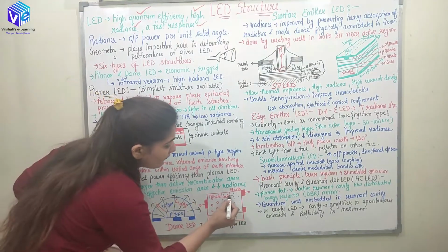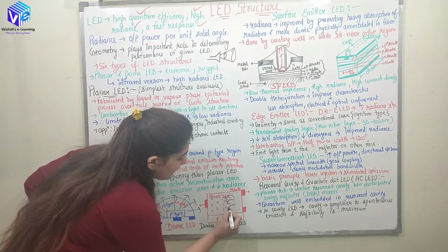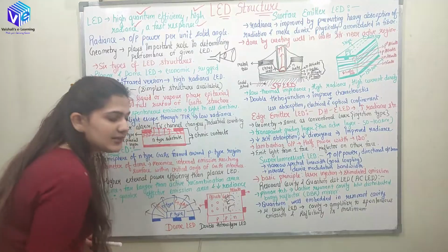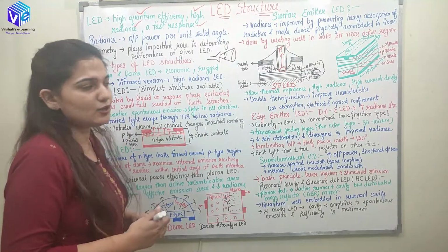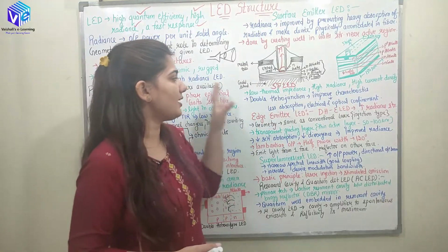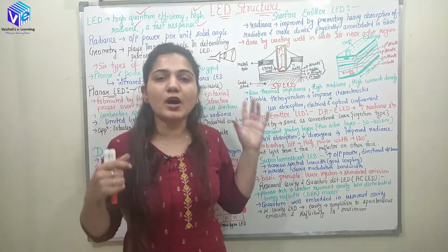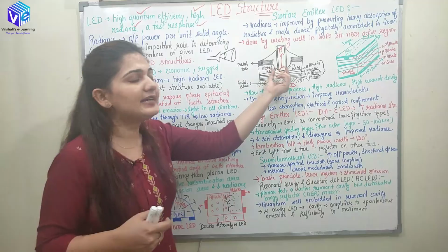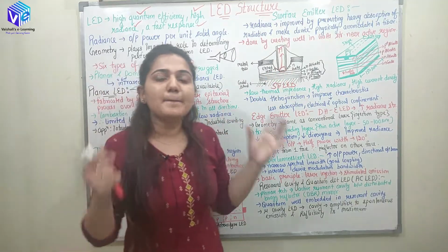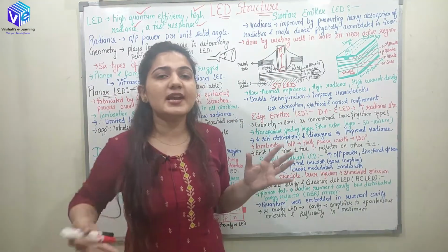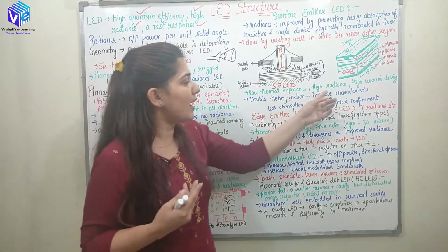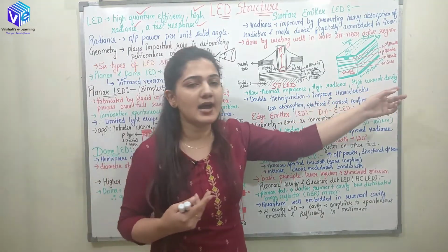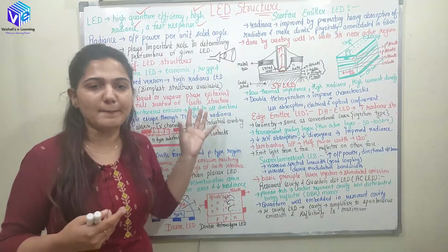A lot of electrons will be coming into the P-type gallium arsenide, due to which it is going to increase the recombination rate. So here I will be having the low thermal impedance inside the active region. When the impedance is low, the hindrance is low, which means the power radiated would be high. So I will be having high radiance and high current density because of the low impedance.